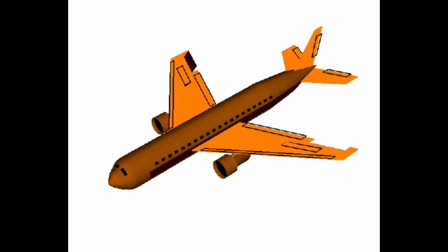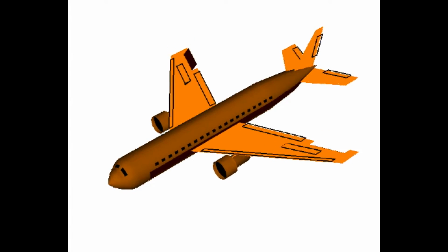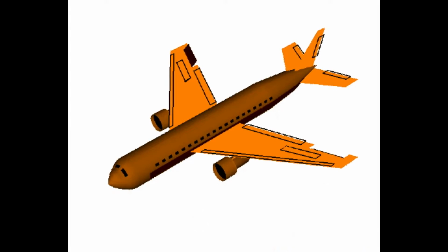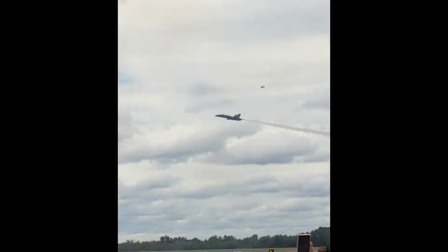The control surfaces that control the rolling of the aircraft are known as ailerons. Ailerons are placed near the outer edges of the wings of each side. They move like this. As the left aileron is deflected upward, the right aileron is deflected downward. As we have learned, increasing the angle of attack on an aircraft will increase its lift. When we deflect the aileron down, it increases the lift on that side. But when we increase the aileron up, it decreases the lift on the opposite side. This results in a rolling motion of the wings.